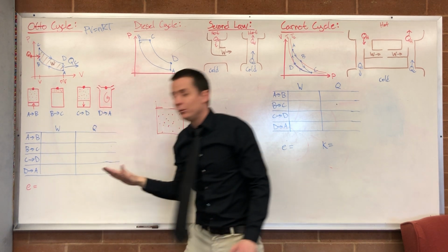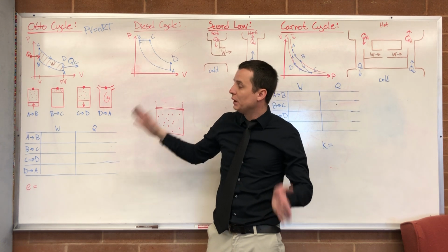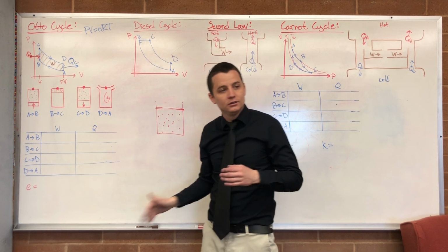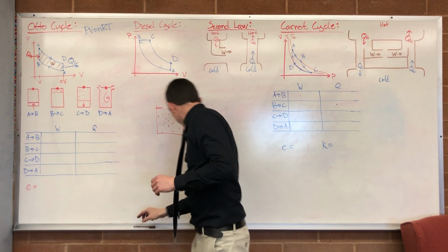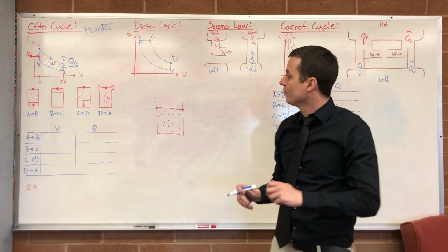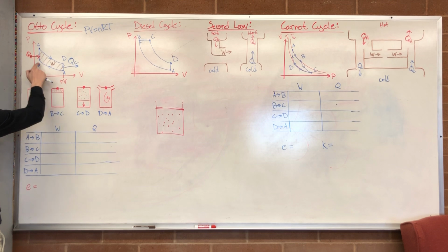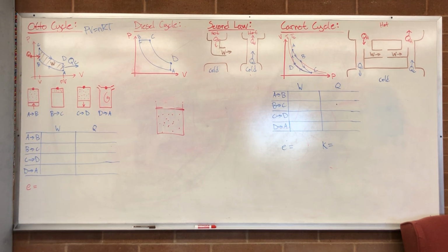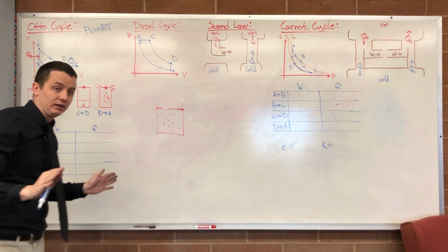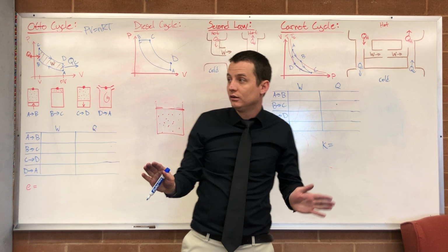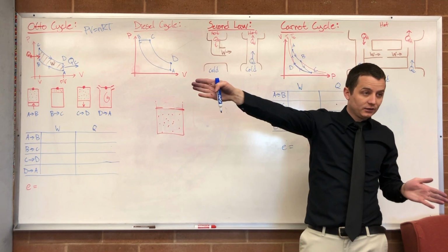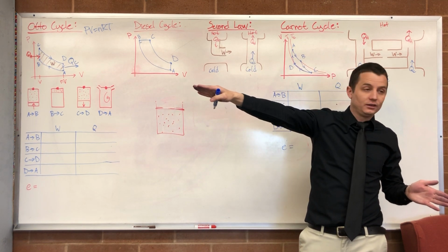So let's once again fill out one of these tables and then identify QH, QC, and the work done. Okay. So going from A to B, what do we have? An isothermal. Not isothermal. No heat is being added. So adiabatic. No heat is added.